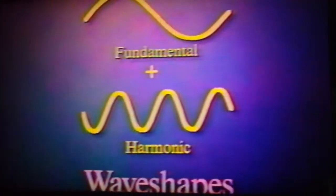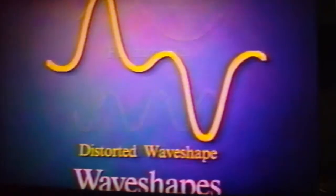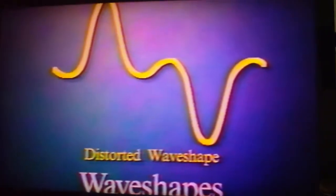Harmonics are frequencies that are integer or whole number multiples of a fundamental frequency. If you strum an instrument in the middle, the strings vibrate at the fundamental or lowest frequency. If you strum near the bridge, the strings vibrate at the fundamental as well as at one or more harmonic frequencies simultaneously. In this way, the fundamental combines with harmonic sine waves to form non-sinusoidal or distorted repetitive wave shapes.